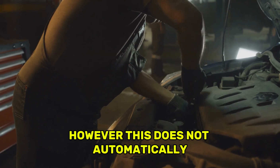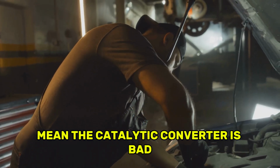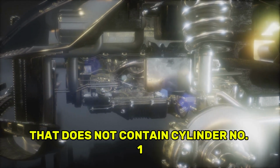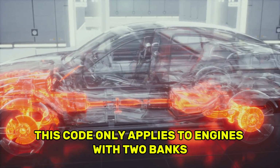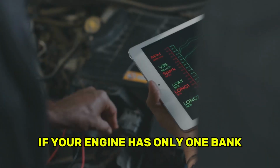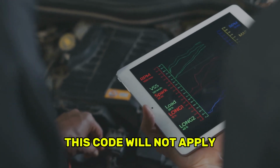However, this does not automatically mean the catalytic converter is bad. Bank 2 refers to the side of the engine that does not contain cylinder number 1. This code only applies to engines with 2 banks, such as V6, V8 and some flat engines. If your engine has only 1 bank, this code will not apply.